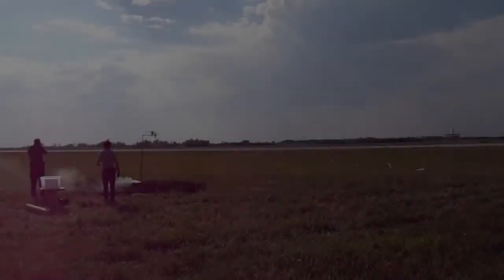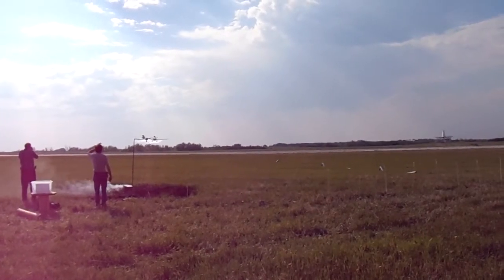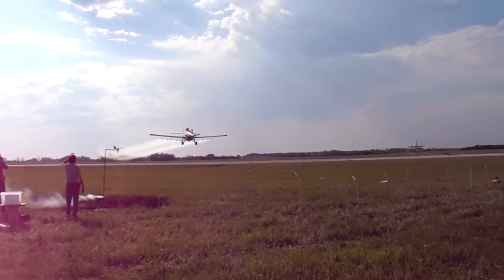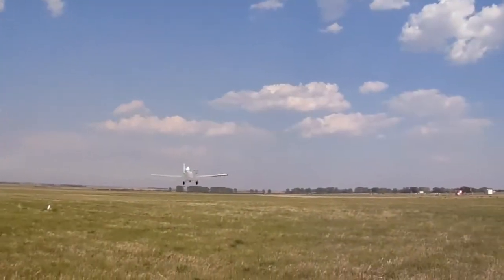And of course, as it evaporates, it gets lighter, so it sediments more slowly or gets entrained more in vortices or turbulence, hangs in the air for longer, evaporates more, and eventually virtually disappears or drifts completely out of the spray area. So it's very important that we minimize the volume of product in these small droplets. So this is achieved by a tight spectrum, and that's what we mean by CDA.